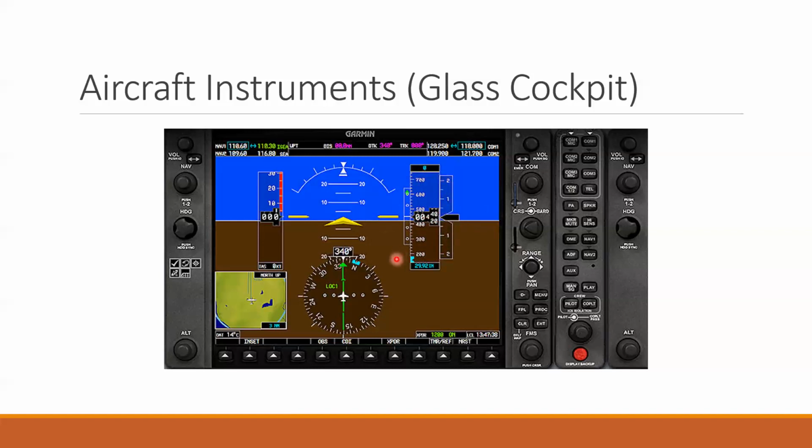And then on the right of that over here, we have the vertical speed indicator. That'll indicate your vertical speed, either descent or ascent. So that's pretty helpful. Below the altitude indicator, we have the pressure. So you can adjust this again for the pressure that you're currently at. And then down here, we have the heading indicator, which has a readout at the top here. So right now we're going like 340 degrees.